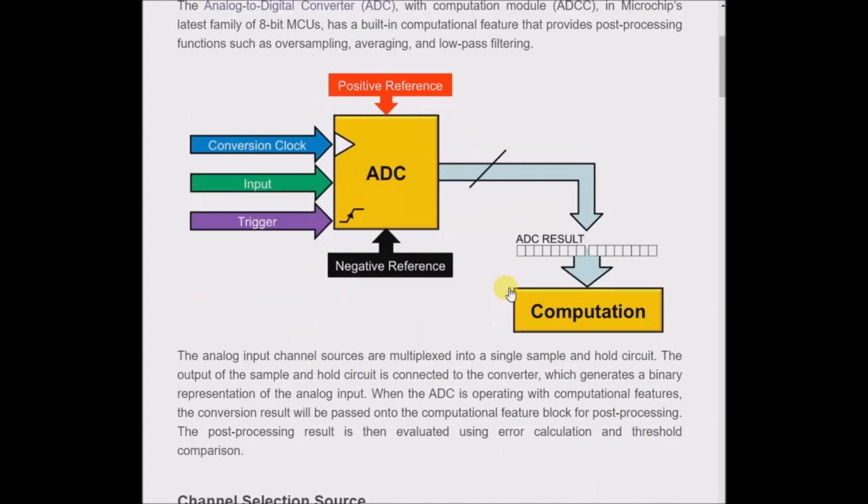Positive reference, ADC, conversion clock, input, trigger, negative reference, ADC result, computation. The analog input channel sources are multiplexed into a single sample and hold circuit.